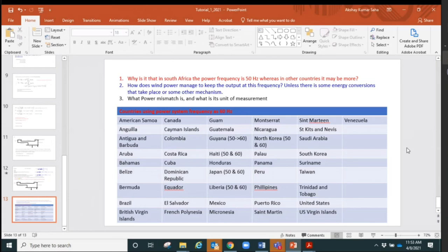If it's not clear, let's say I have a swing bus where the generator is supplying 50 megawatt and 40 megavar, and it doesn't matter how much load is connected. Now I start the load flow study, and I find that after the first iteration, my P is 45 megawatt and Q is 32 megavar. So it's not making any close approximation to the 50 megawatt and 40.